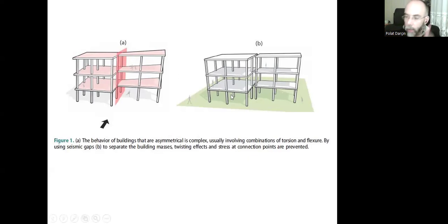We completely separate the buildings, including the foundations, the roof, the floors, the doors, the walls, everything: two separate neighbor buildings. First, we construct this one, all the construction is finished, and then we leave only a 5 centimeter, or 3, or 7, or 10 centimeter gap. It can be calculated by a structural engineer.